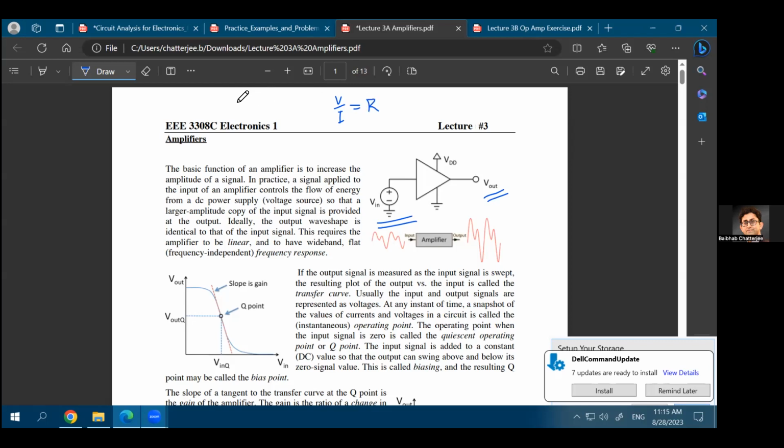So if you know about capacitance, the impedance of a capacitance is 1 upon j omega C. Right? So this is dependent on omega, which is the angular frequency. Similarly, the impedance of an inductor is j times omega times L, j omega L. That is again dependent on frequency. So impedance is a more generic overarching term than resistance. So resistance only means voltage over current.